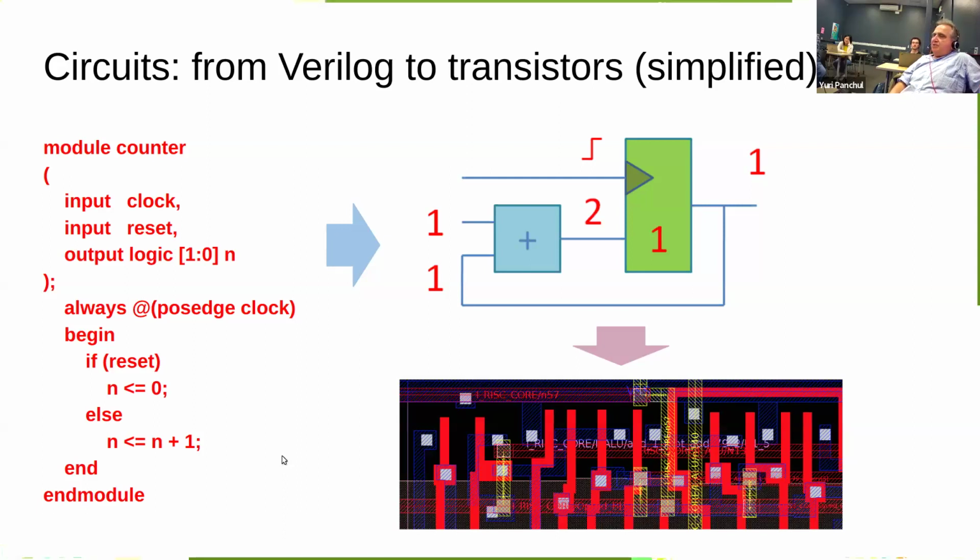And Rick was sitting there at an alphanumerical display where components in a chip were pictured with stars and minuses and pluses. You use the cursor and connect those components together. This is the way you enter schematics. Some of those components are gates, and other components are D flip flops, and so on and so on.